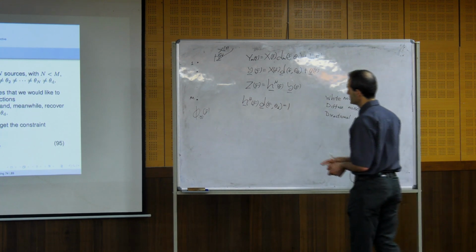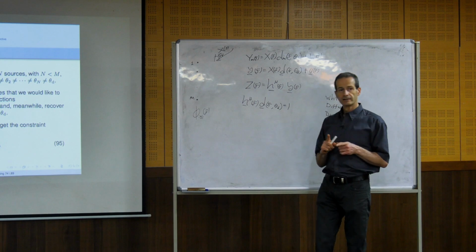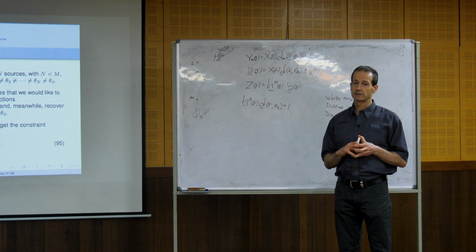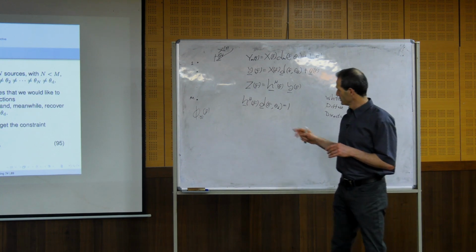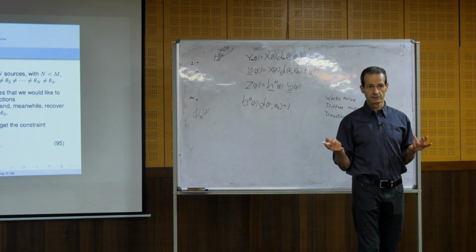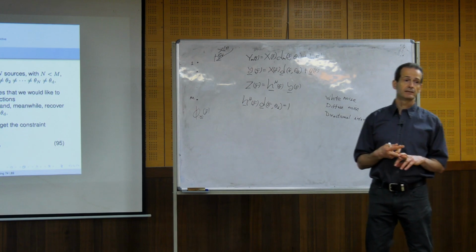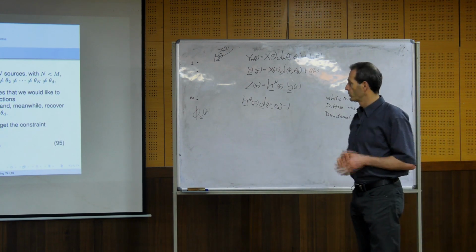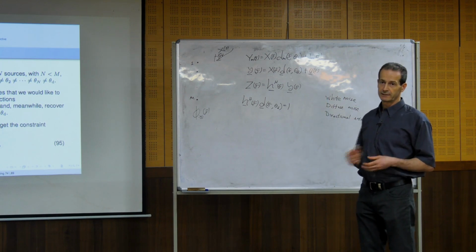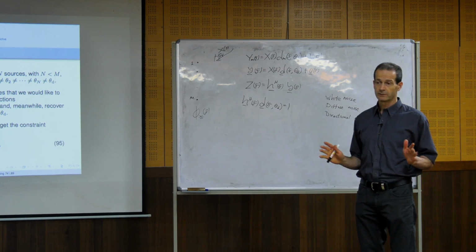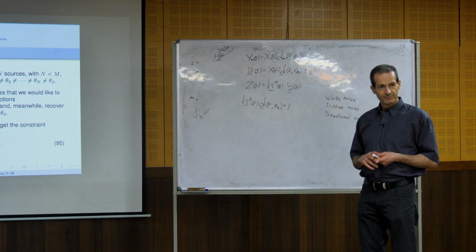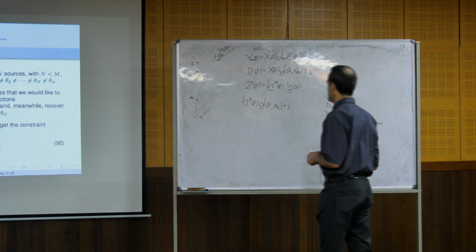Okay, so this is a constraint which we see is different from what we used for multi-channel signal enhancement. In multi-channel signal enhancement, we used such a constraint only when we talked about distortionless response: MVDR, LCMV, GSC, okay? With beamforming, we have to use it for any beamformer that we want to design. Otherwise, we cannot control the distortion. Maybe the distortion will be such that we don't pick up the signal, okay? Okay, so this is important.